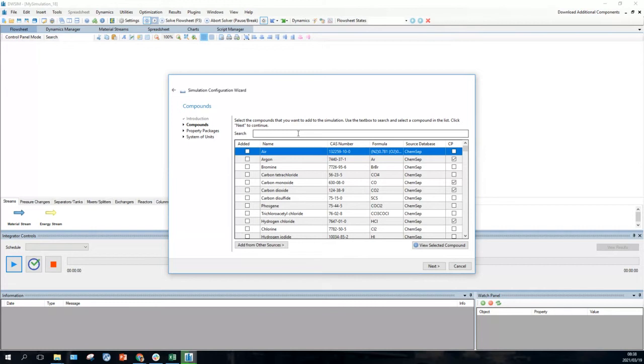So it's just a tank. You have a pipe going into a tank. It operates at a certain temperature, and therefore you'll get a certain amount of liquid coming out, and you'll get a certain amount of gas coming out. And they will have different compositions because we have different vapor pressures for the two.